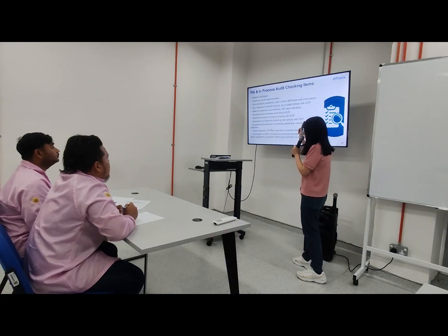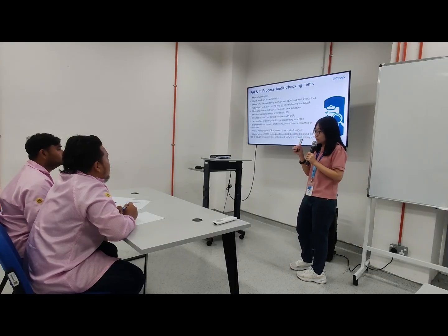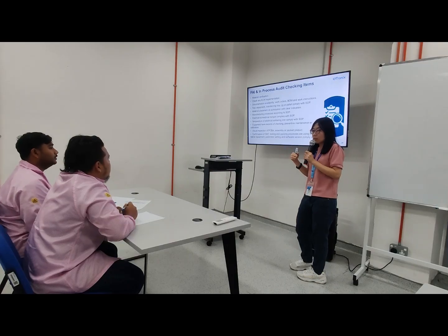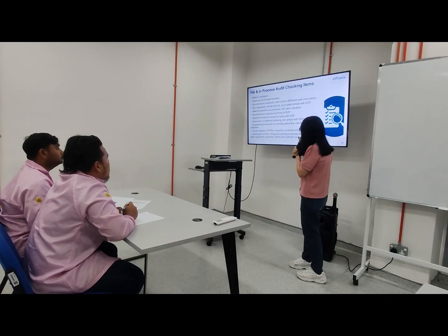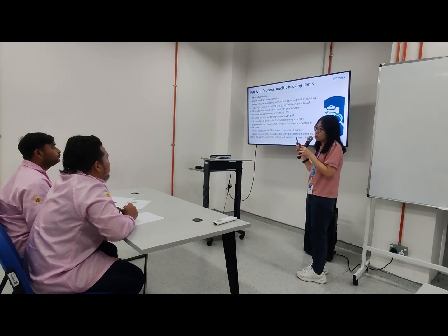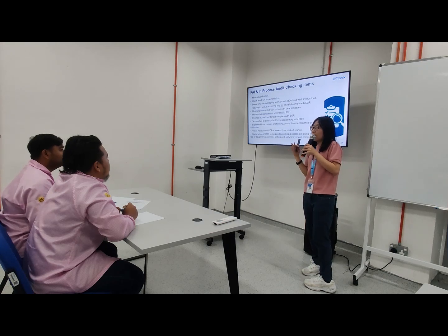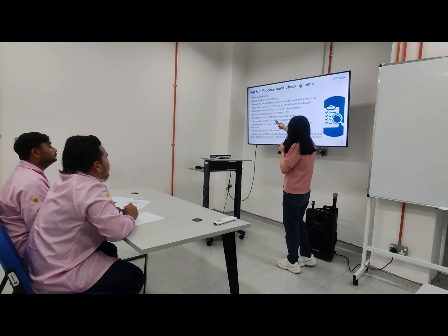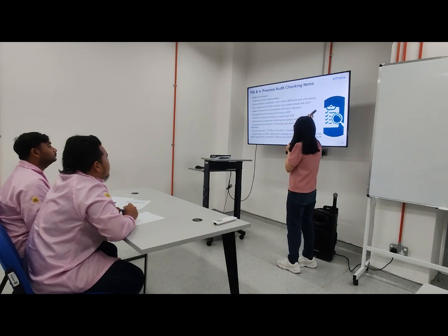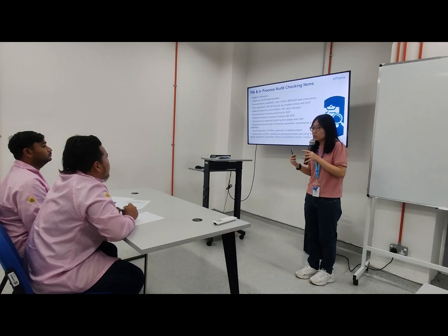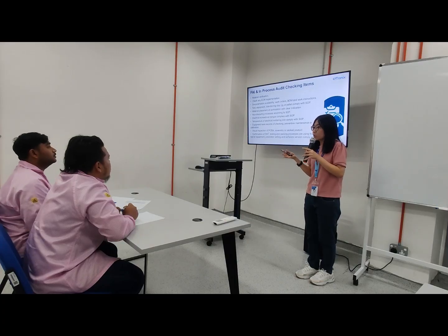Next, we will check any ECN implementation. For example, for this WO, we will check whether this WO got any ECN. Then documentation availability for work orders, BOM and instructions. We'll check whether all these documents are available and whether the operator follows them. Then the tools and equipment, transferring tray, jig or pallet, complying with the SOP, meaning the operator is using the correct jig, correct pallet, or correct tray.